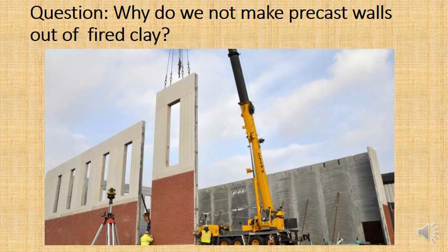shapes like that, it's very hard to heat the clay, because basically it's going to get heated on the surface, but in the middle it's still going to be cool, and so you're going to end up with parts of the clay which are going to be on the surface where it's going to be very hard and strong, but in the center it's still going to be soft and weak. So there's sort of a maximum size that you can use when doing fired clay.